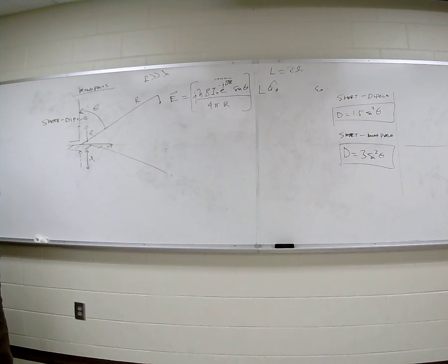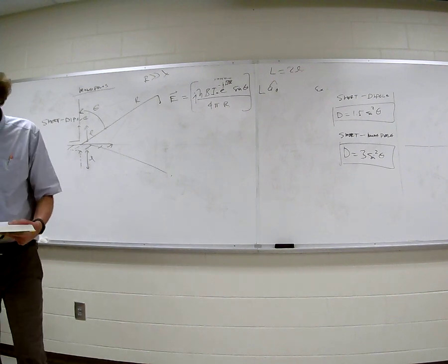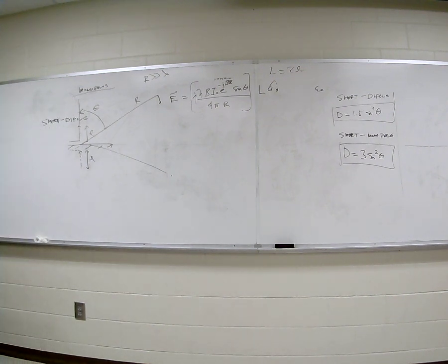If you also look at the gain for a second, for a half wave dipole, the peak gain, or directivity I should say, is 1.64. Do you see that? How many have books here, by the way? Some of you don't. I want to make sure everybody's got this right. You see there, 1.64? The directivity doubles. That's right.